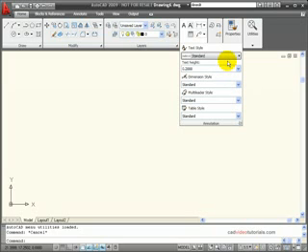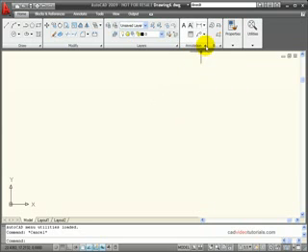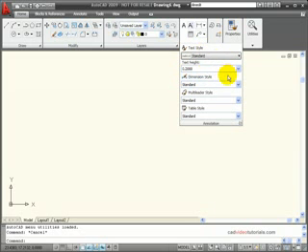And because annotation is style driven, it has to be turned on. Now, it's not turned on by default in my styles when I start a new drawing from scratch. But you will notice that, for example, under dimensions I have a standard style, and in the flyout I have the option of an annotative style. My annotative style is basically my standard style in terms of all my dimension variables, but with annotative turned on in the fit portion. So I'm going to turn on annotative and use that for my dimension style.